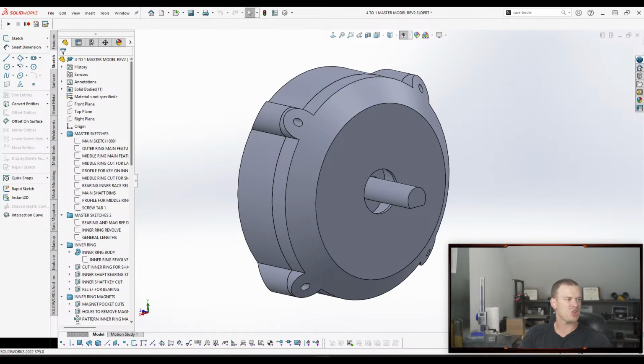So you can share that skeleton sketch part. You can all work off of it at the same time because it's just bringing it in as a reference and then you're deriving the sketches from it. So you're not actually editing or doing any work within that part file. So more than one person can have access to it and can design from it, but they can't edit it.